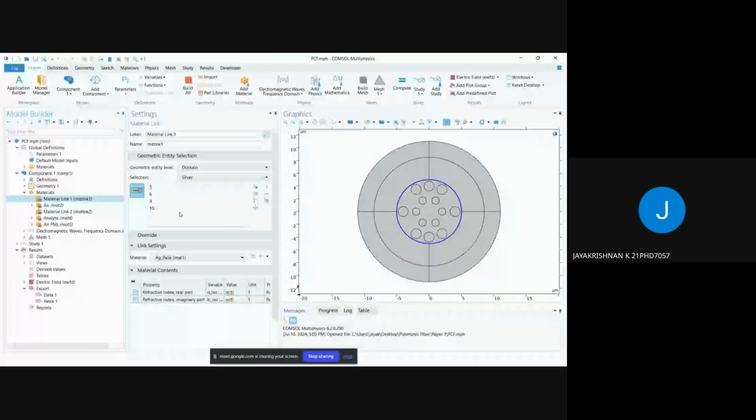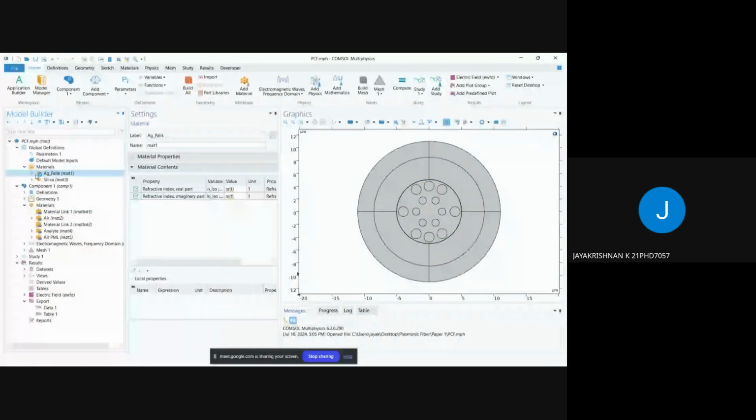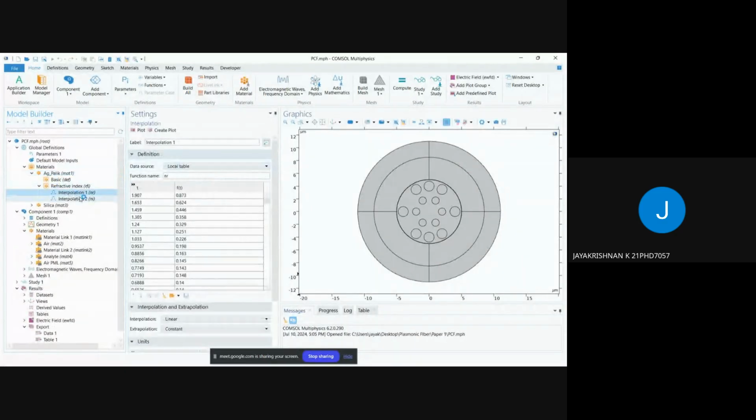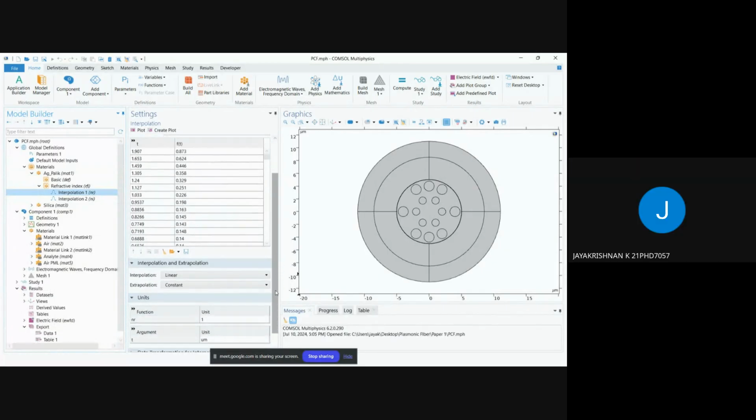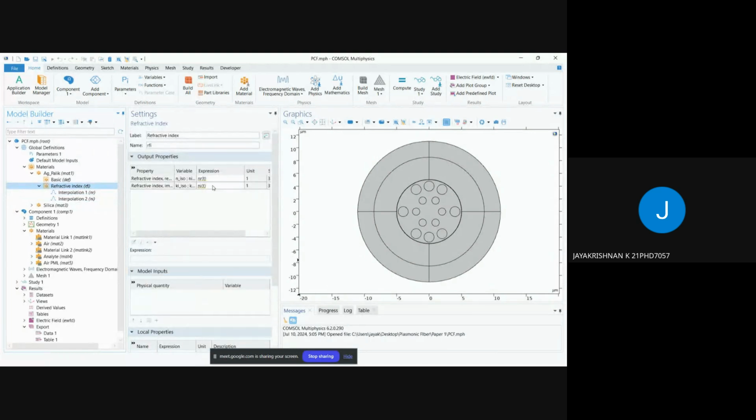So this is my structure actually. I have added the materials in the global definitions, which is using an interpolation function. Can you see this, sir? I have defined one micrometer and all those things. Here I have written it like this, and I'm getting a yellow underline showing unexpected unit of input, but it is not doing anything to my results. It's just a warning.